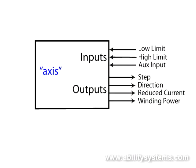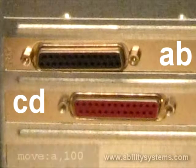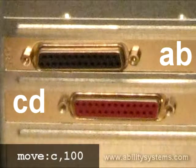Signal names identify the output pin within the set. As mentioned, the axis designator physically determines the applicable set of signals. So, for example, if the command move :A, 100 generates 100 pulses from pin 2 of the port you labeled AB, the command move :C, 100 would generate 100 pulses from pin 2 of the other connector labeled CD.